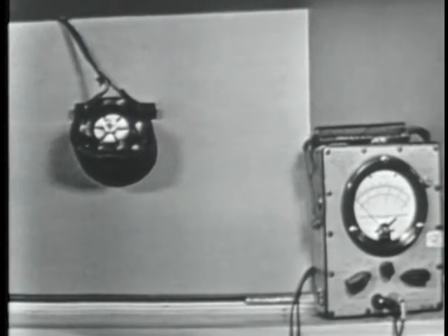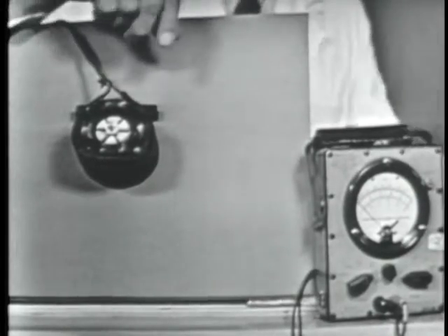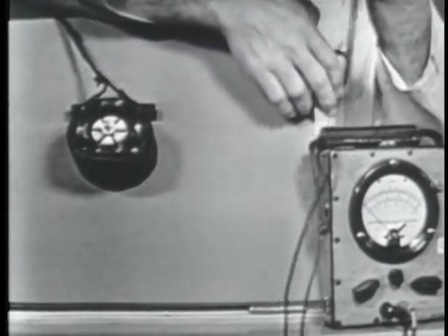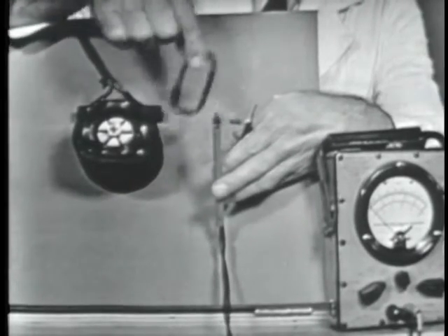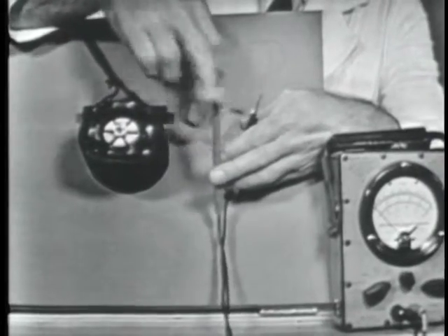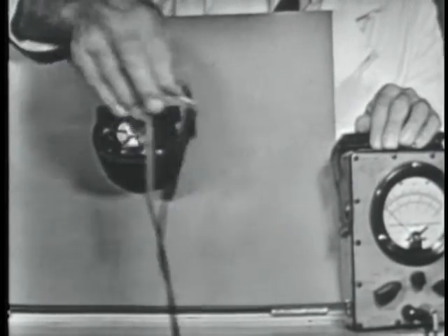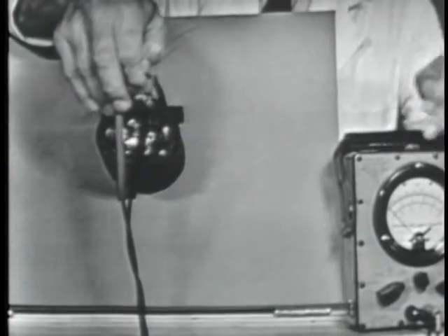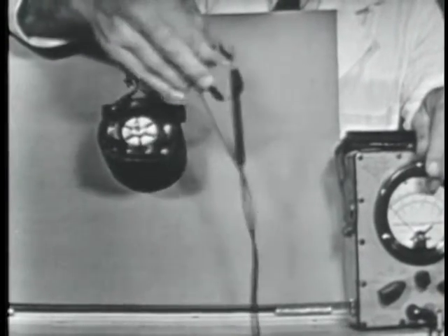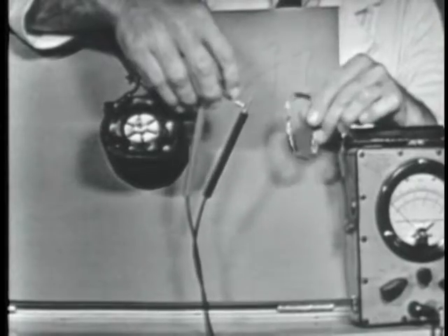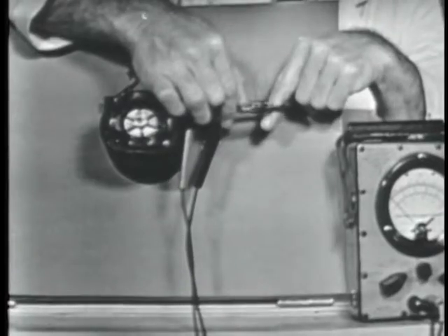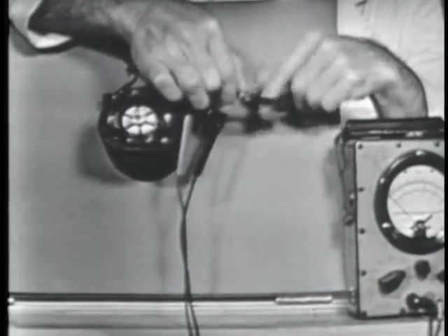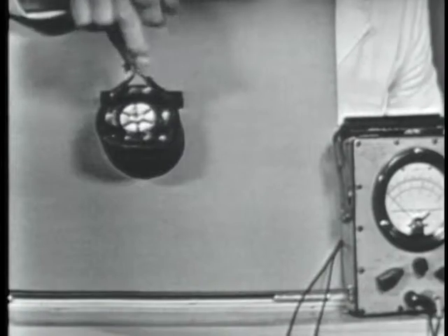All right, item 4, the rotor acts like a magnet. Well, it actually becomes an electromagnet and follows the rotating magnetic field because of induction. Okay, and we proved that with this little loop of wire, the resistor and the PSM6. We put the loop in the field windings, and the PSM6 showed us that we did have a voltage induced into the loop, causing current to flow. Once we had current to flow, we know that the loop had to become magnetized and exhibit a north and a south pole. And once we get it magnetized, it has got to follow the rotating magnetic field.